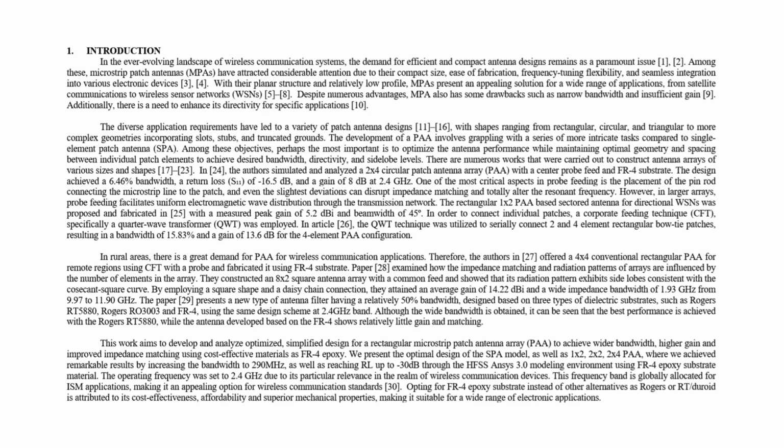Different patch shapes like rectangular, circular, and more complex designs have been explored to meet specific requirements. Building a patch antenna array introduces additional challenges, especially in optimizing performance by carefully adjusting the geometry and spacing between elements to achieve ideal bandwidth, directivity, and side lobe control.